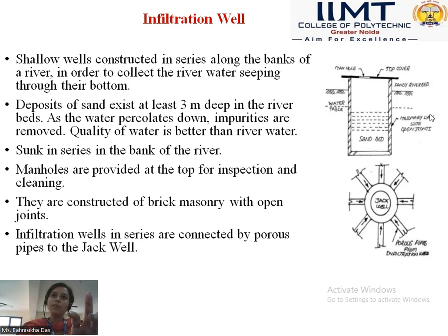So all the river water will seep through the soil and come into this infiltration well. These wells are constructed in such a way that they are open at the bottom and covered at the top. So all the water which is seeping through the river, because of the head difference or pressure difference from the river to this particular area, will seep in and fill the infiltration well.